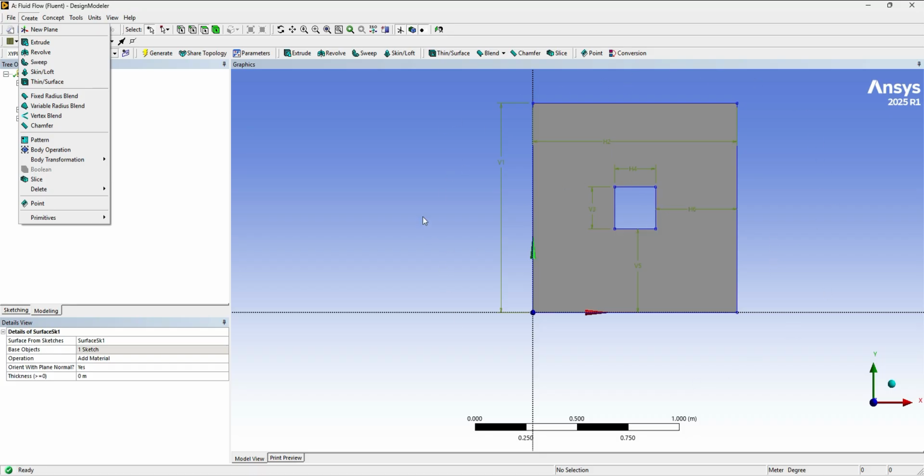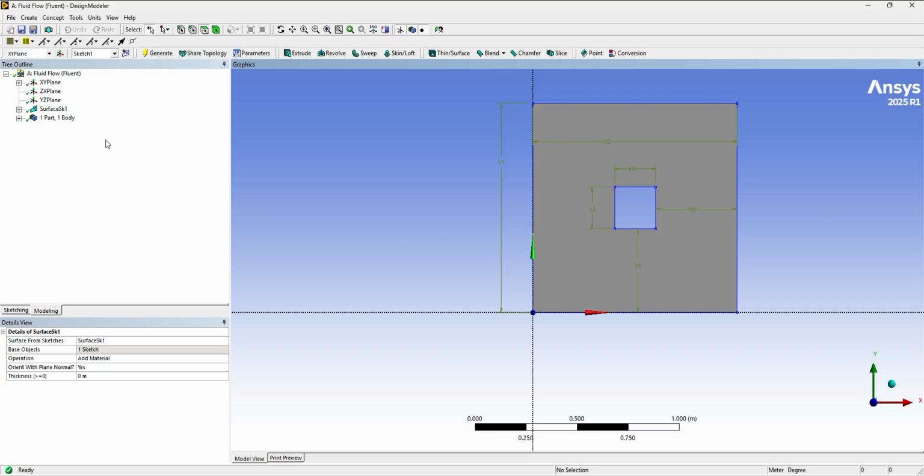But right now, since we are already here, we do not need to use the Boolean operation, but you do need to explain it in your final wrap-up, just a little bit of why you would want to use it. The idea is pretty simple. If you create two different squares and add them on top of each other, you will have two sets of squares that you need to subtract one from the other. But our geometry is ready for now, so I'm going to close this